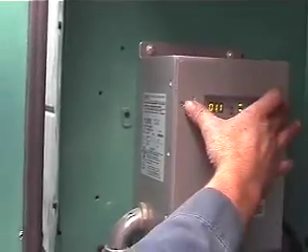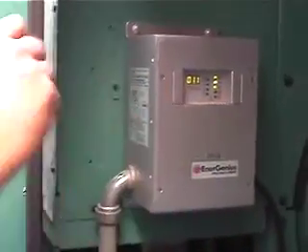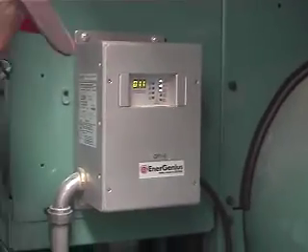To change those, you can pull these 4 screws off and go inside, and you can change if you want your battery voltage a little bit higher. It's a multi-tap voltage. Also, you can either do 220 or 115 if you ever need one in the future for something else. If your red light comes on, it tells me your block heater's not coming on.